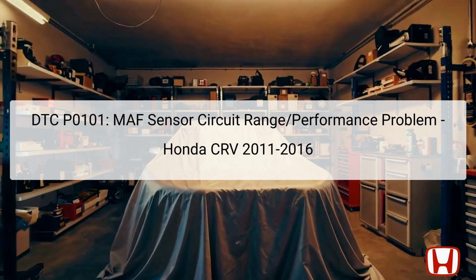The DTC P0101 alert identifies an issue with the mass airflow MAF sensor's circuit range or its performance. The MAF sensor plays a crucial role in measuring the amount of air entering the engine, which the Engine Control Module, ECM, uses to calculate the optimal fuel-to-air ratio. This relationship is vital for efficient engine performance and emissions control.